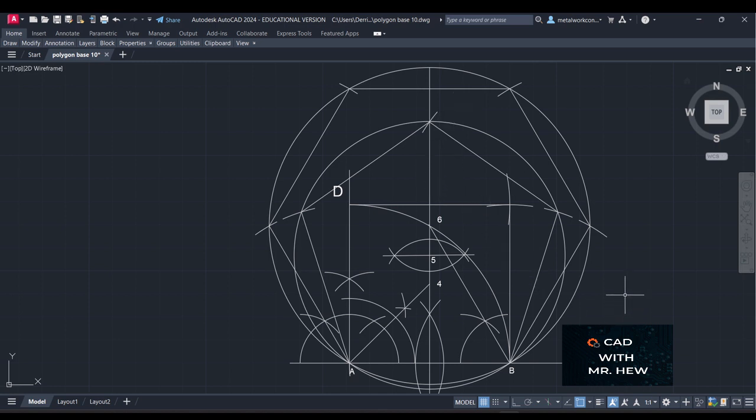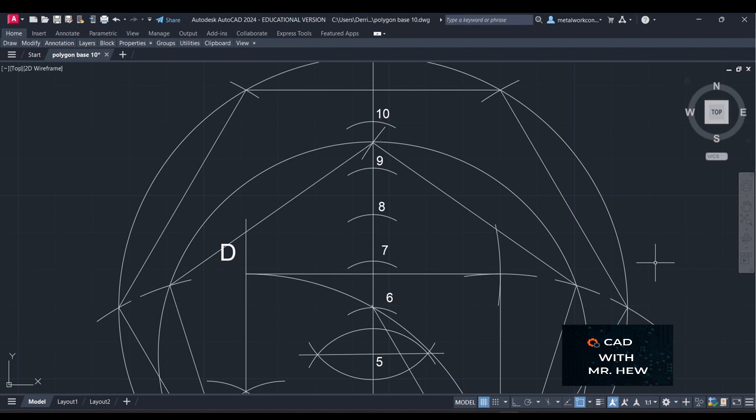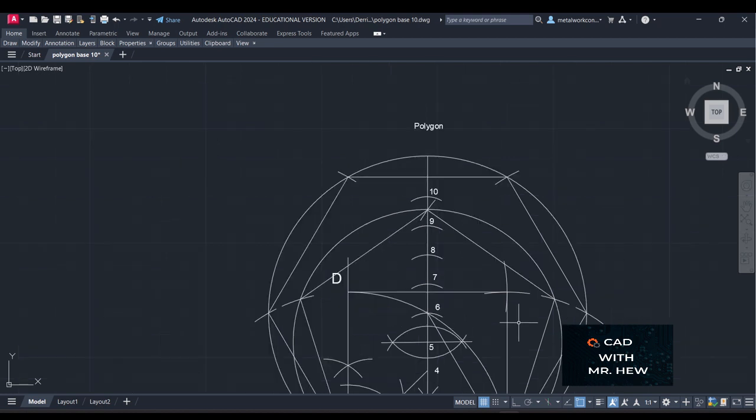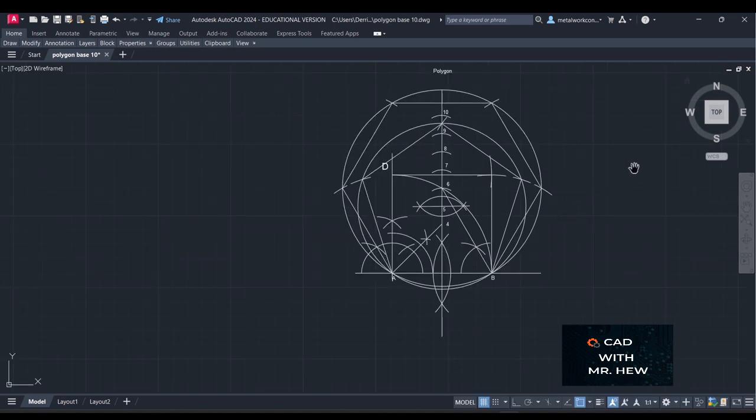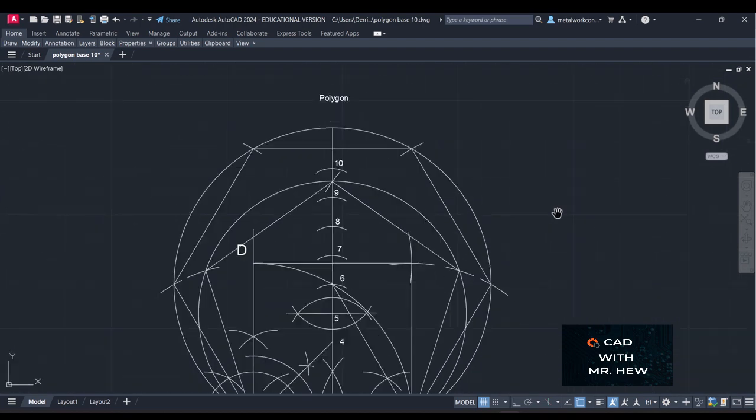All right, so let's do that. All right, what I've done, I've marked arcs as I told you from 6, 7, 8, 9, and 10. The same radius was this distance from 5 and 6, right? So the circle drawn with the center at 7, which is right here, with the radius of 7B. When you draw that circle, when you mark the sides AB, starting at B, you'll get a 7-sided figure, all right? So let us finish that, all right, for completeness, all right?